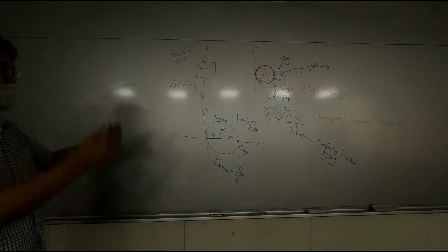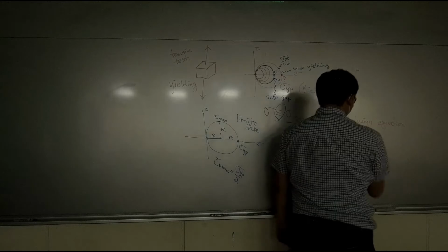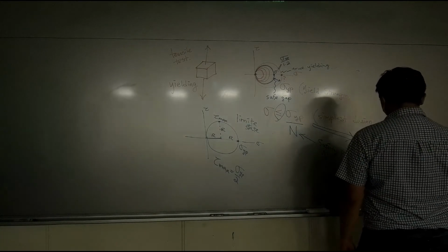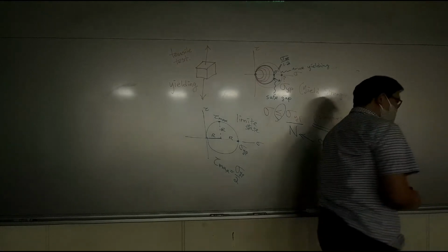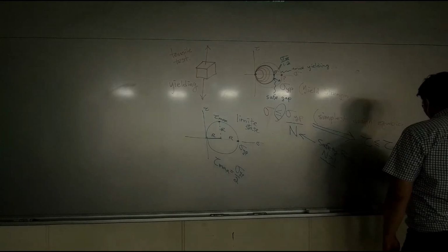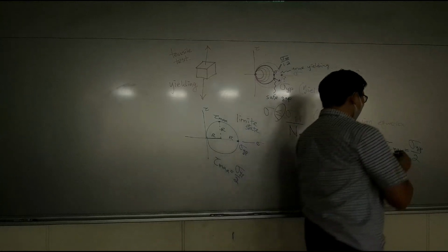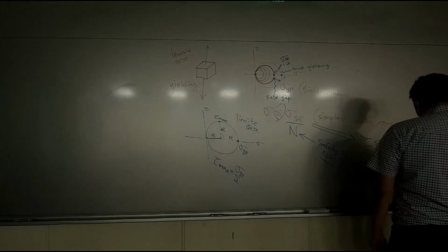So at the end, you can convert this design equation into a different design equation. Shear stress must be smaller than the maximum shear stress that you can allow, and it's actually half of sigma yp. With safety factor, if I put an n right here, then I have an n right here.